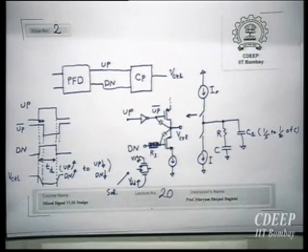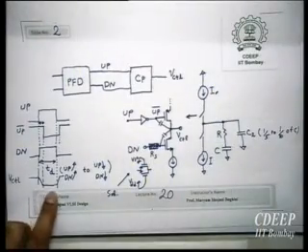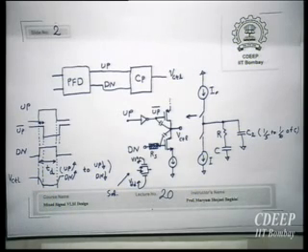After all, the loop is locked. When the loop is locked, in the lock condition the average current given to the VCO will be almost equal to 0. And this average charge will be almost 0 in the locking condition. So here there is a disturbance, so some charge is given and some charge is taken. During that time there is a small change, but that is compensated by that phase error, so that it doesn't come into the picture. So that phase error will be sensed at the end.